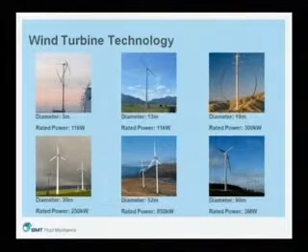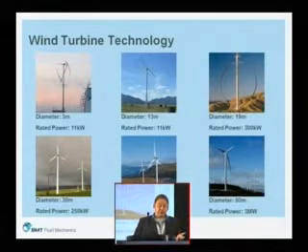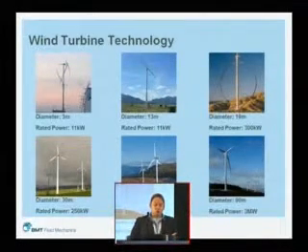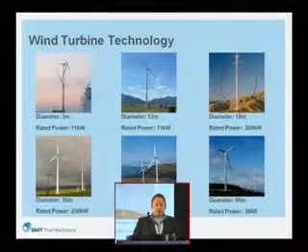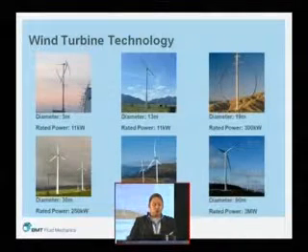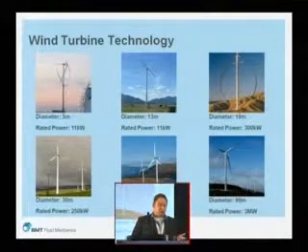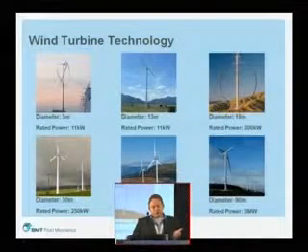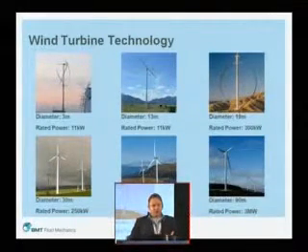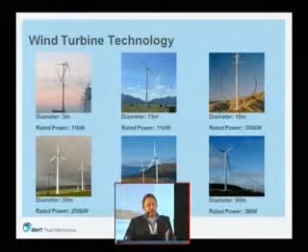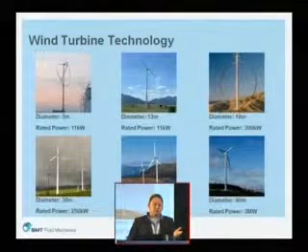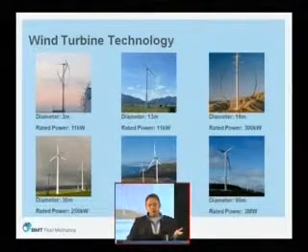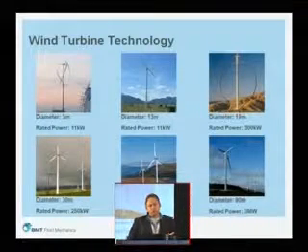If you're considering extracting a meaningful amount of power from the wind, say 10% of building consumption, you're talking about devices which are rated in the order of hundreds of kilowatts. So if you look at the other turbines there, you are immediately talking about devices which are tens of meters in diameter. Typically, a 30-meter diameter turbine gives you something like 300, 400 kilowatts.